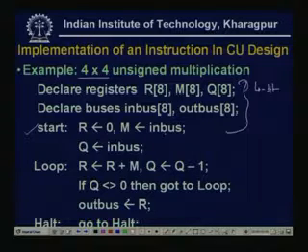That means, one is multiplier, another is multiplicand. Now, as it is a repetitive addition, R is R plus M. That means, this multiplicand M will be added Q times, then it will give QM.